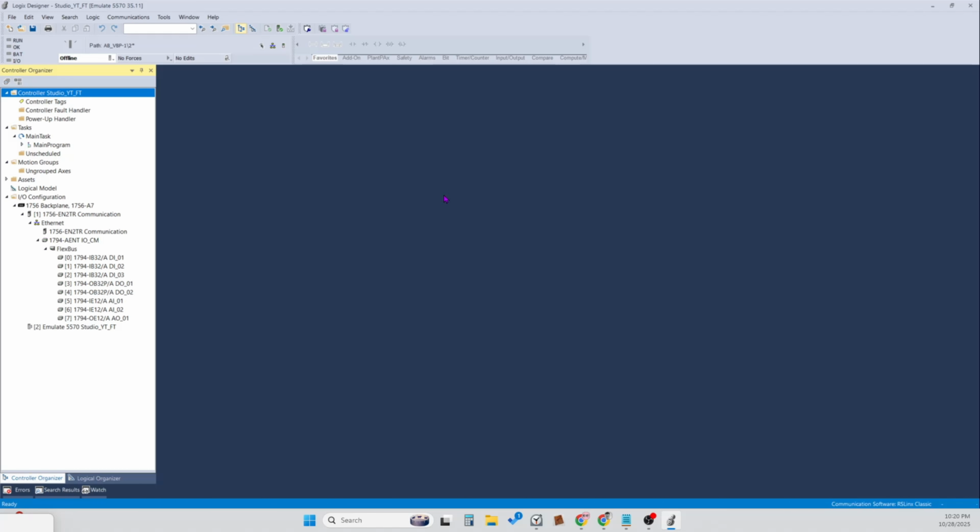In this video, I will show you exactly how to use numeric input to send a value directly to the PLC. We will create a timer set point entry using Studio 5000 and FactoryTalk View. So let's get started. First, you have to create a tag.